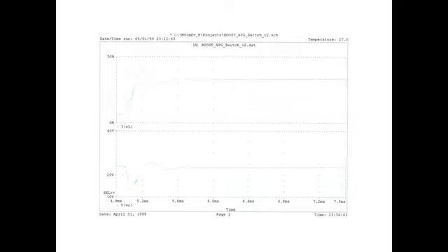What does the average model say will happen? There it is. So the thing I want to point out is even though that's a pretty big load step, the average model does a really good job of capturing what goes on, right? So you can really get behind averaging as a way to get a simple look at what your system's doing. And in fact, if you calculated what the oscillation dynamics looks like, the small signal model still looks pretty darn good. All right?